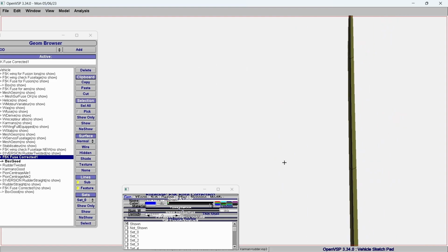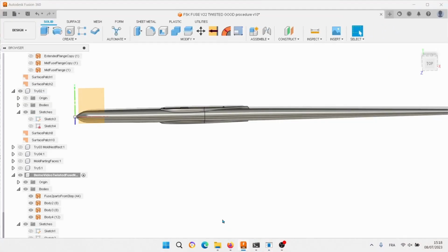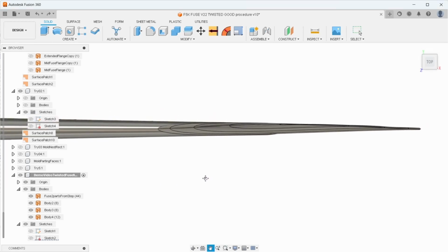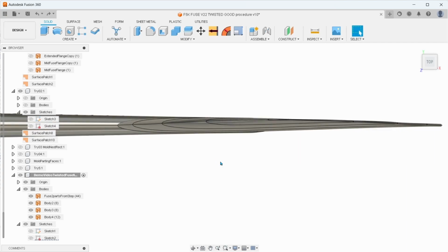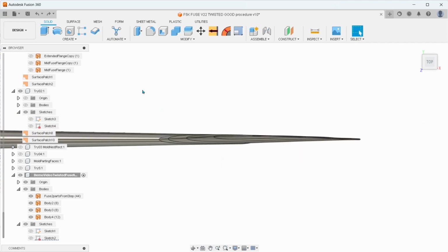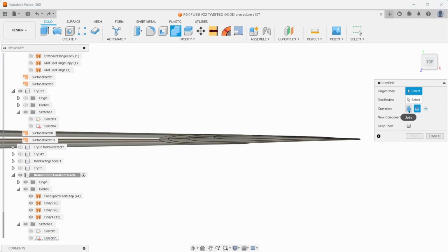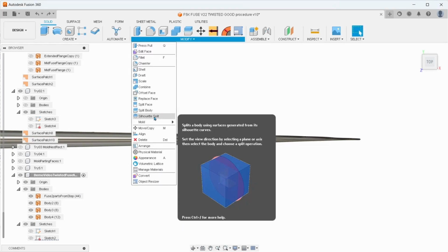At the end, this is the import that had been done under Fusion 360. Look at my other video to check it out. We can see that the rudder is twisted. It's more obvious here. You cannot use combine with a cut, which we usually do for a symmetrical mold, and just use a split body with, for example, the x-axis or y-axis.